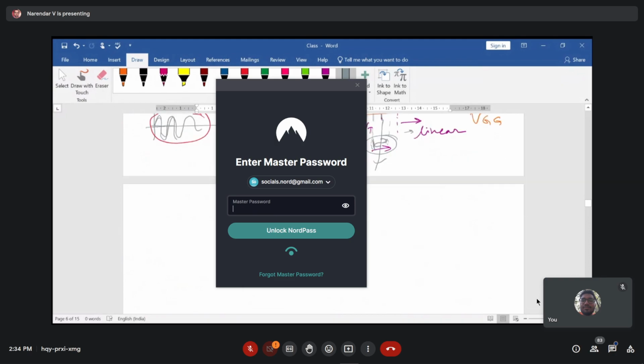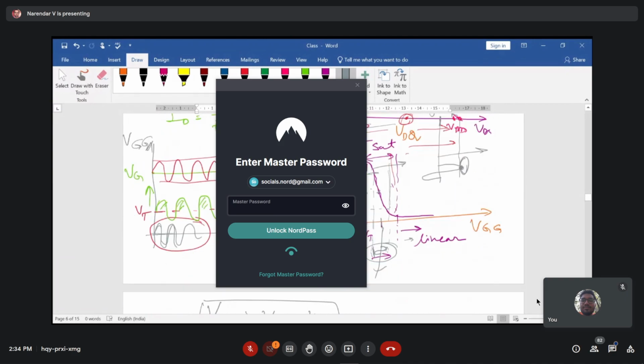Okay. So during this process, what you need to focus on is that the VDS value should be greater than or equal to VGS minus VT, which ensures that the transistor is in the saturation region of operation. Okay. Now, if we do the AC analysis for a resistive load, going back to the resistive load in the common source amplifier, this is what is depicted over there.